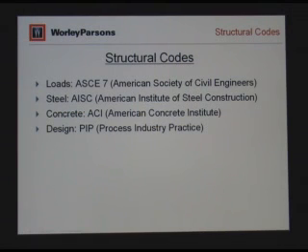But anyhow, as I mentioned, for steel, our main code is the AISC, American Institute of Steel Construction. It's currently in the 13th edition. When I started design work quite a few years back, we used to refer to the black book. It was about an inch thick. Now it's about 2 inches thick, and there's an accompanying CD. So there have been quite a few changes.